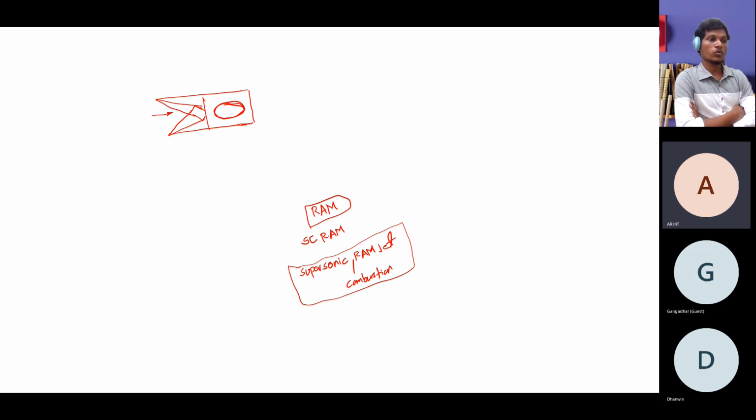In the same way, you can also use source and sink singularities. A flow over a source and sink with a minimum gap between them is what you can call a doublet. A doublet is a primary singularity that you mostly see from a theoretical perspective rather than a practical perspective, for the modeling aspects, to model a flow over any complex object.